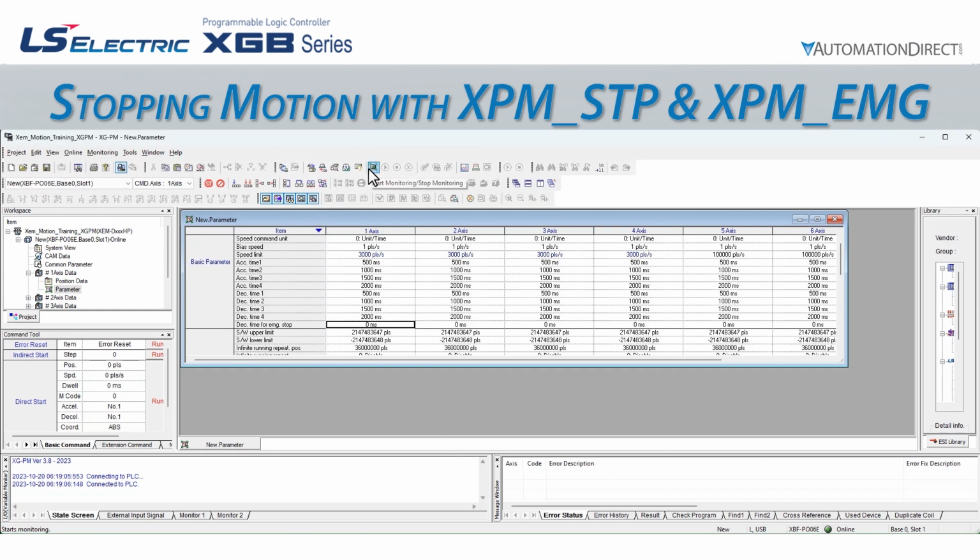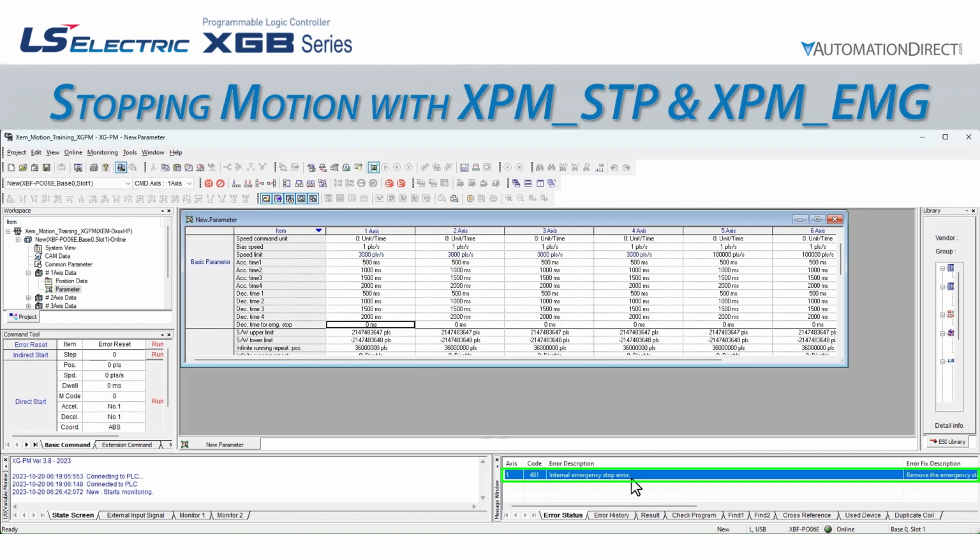Let's also take a look at the axis view in the XGPM software. If we go into monitor mode, we see that the axis is faulted, and the message window tells us that an emergency stop was executed. Perfect! We stopped very quickly and will not be able to restart unless we execute an axis reset. This is the perfect behavior for the emergency stop in our example.